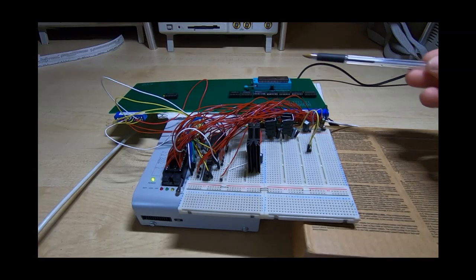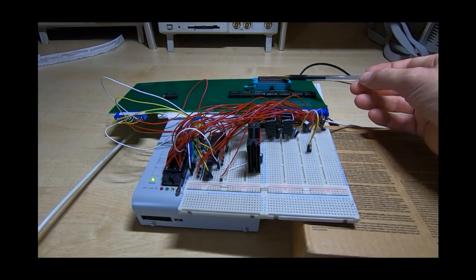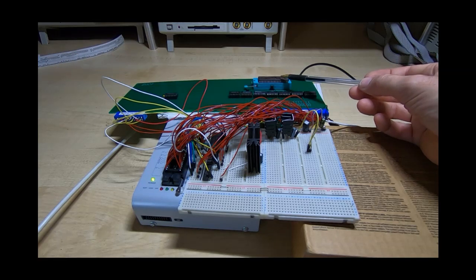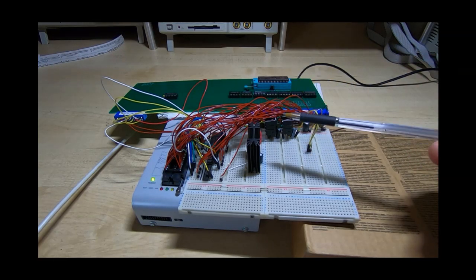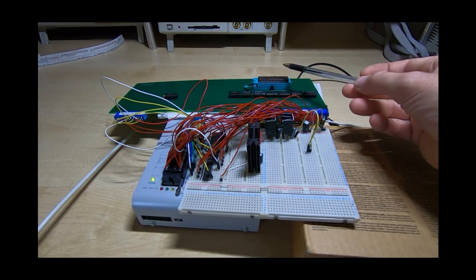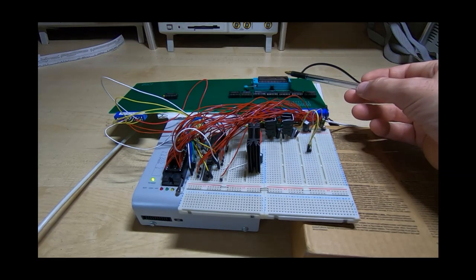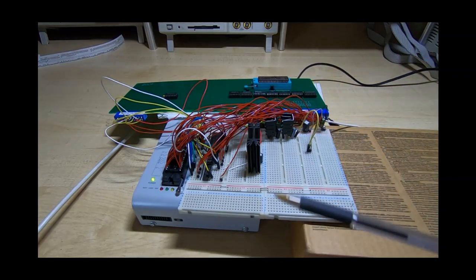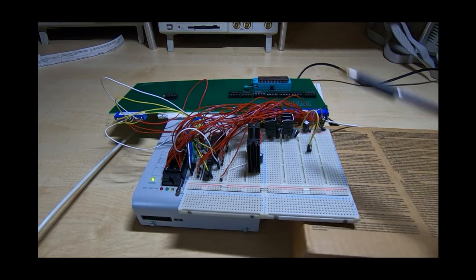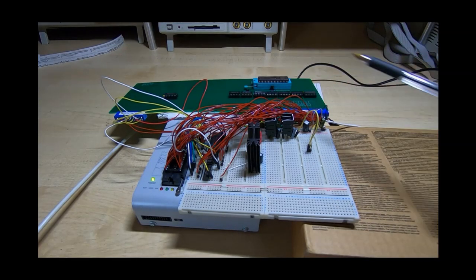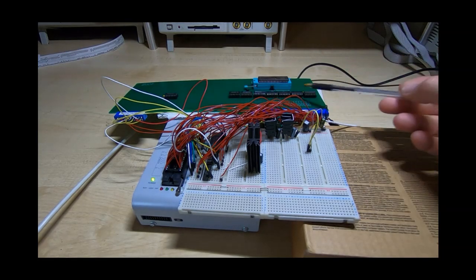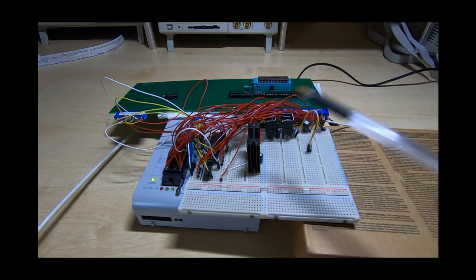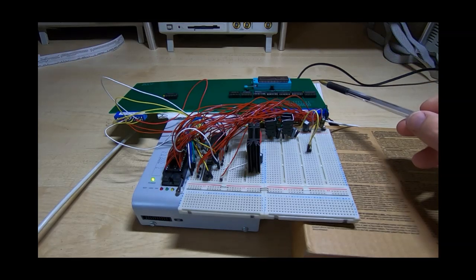So what I'm doing here is I've constructed a single file from the dump files from the emulator. I've converted that into a single binary file, and then I've programmed that into the ROM. Bear in mind that the data is actually inverted, so what you see when you read it out, what's actually stored in the ROM is the complement of that, because the data is inverted when it comes out of this card. So once you've taken all that into account, in theory what I should now be able to read out